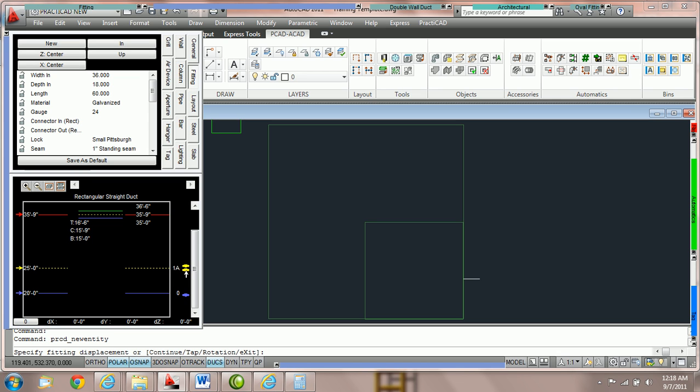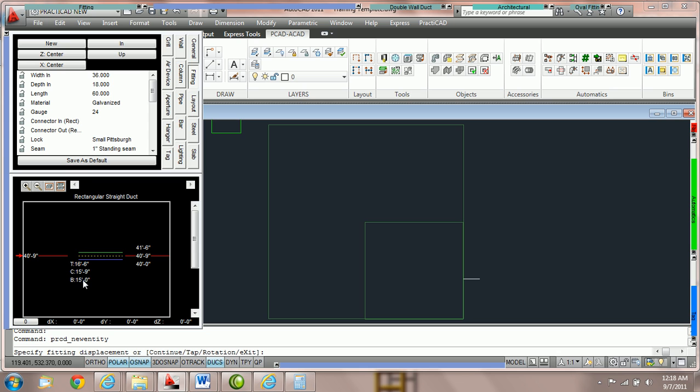However, if we switch our new relative mark 1A to relative bottom, you'll notice that these values will change. So if I put 15 foot in here now, that means 15 foot above whatever relative bottom happens to be at that point in time. If we've set 25 foot to relative bottom, and we said be 15 foot above it, we're at 40 foot in absolute elevation. So we can toggle between what's relative bottom, and it does not have any effect on our tags, and we're going to show that to you now.